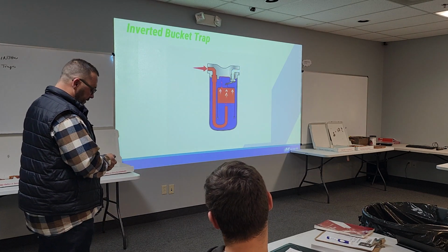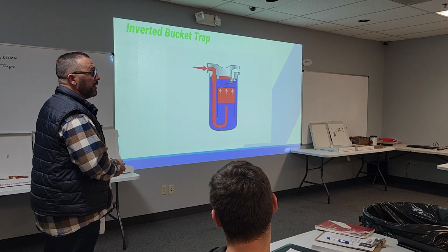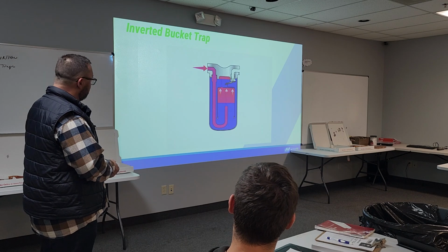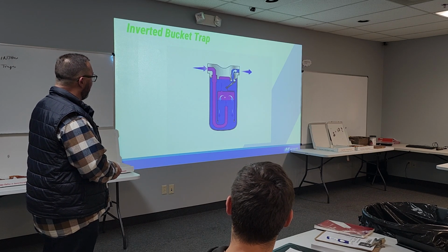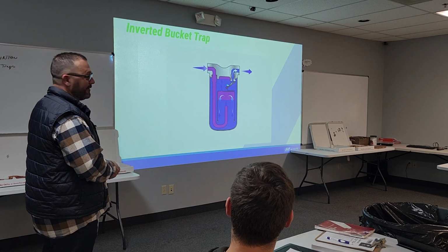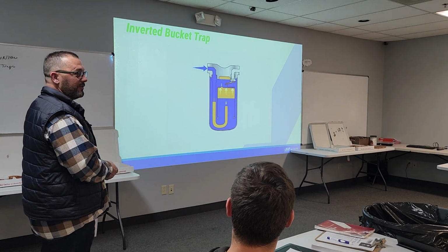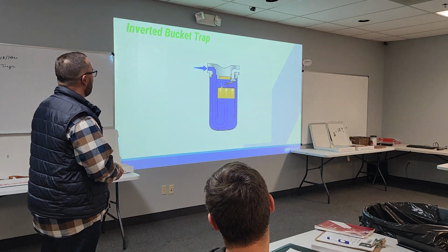And for a trap that struggles to vent air or even decipher air from steam, what's going to happen when air hits that trap? That bucket is going to become buoyant, and it's going to close off that head and seat. And all you're doing is backing condensate up, and your system's not going to heat up.